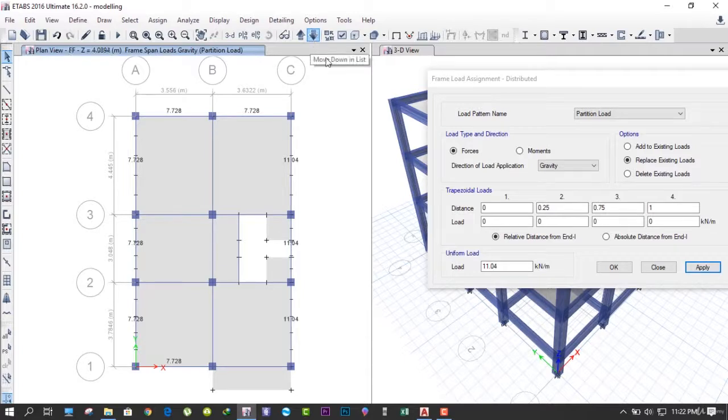So now we go to first floor again. So after that, what we see is that we got a full brick wall with opening over here and over here. So what we do, we just multiply this value into 0.7 and we click on apply, right? And same goes on the second floor as well. So we click on apply, right? Again we go on the first floor.